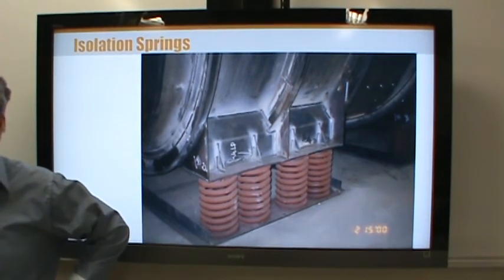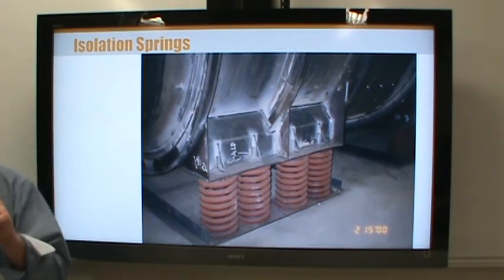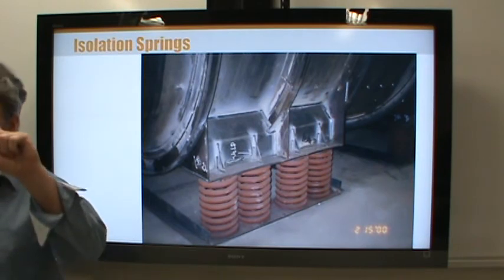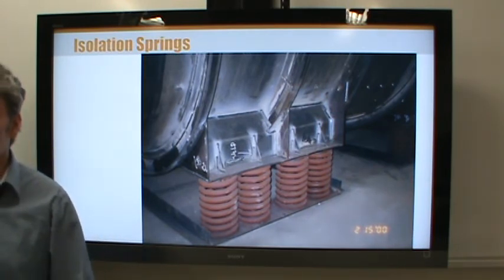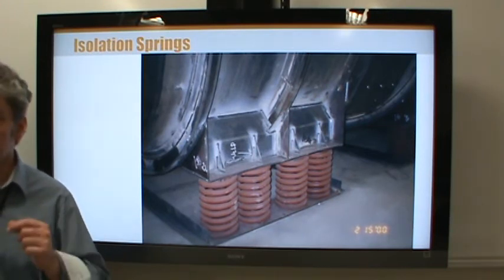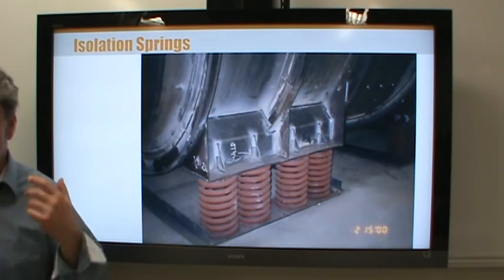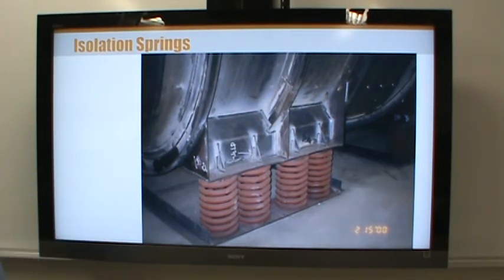If there was too much clearance between each coil, wouldn't it have a tendency to bow? That's a good question. What about buckling? What about when the spring comes out of plane? Now, I'm sure you've all taken apart a ballpoint pen that you can click, right, and found the spring, and you start to compress it, and all of a sudden it flies outside of this, right? There's a name for that. That's called spring buckling. Okay? And one of the design parameters we'll care about a lot is at what force and deflection will the spring buckle, or will it at all? That's something we care quite a lot about.